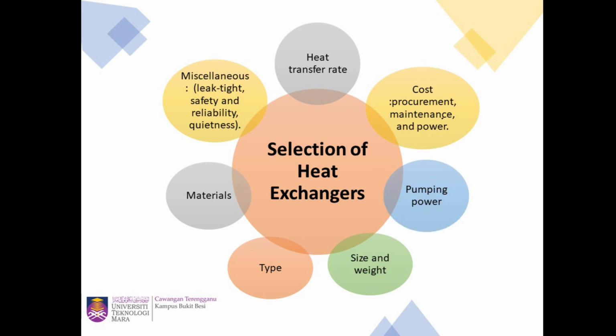Most importantly, the size and weight, the type of heat exchanger, and what materials are being used for the heat exchanger, so that we have to make sure it is compatible with the fluid that we're going to use. Last but not least are other miscellaneous factors, including whether the heat exchanger is prone to leaking. We have to consider safety and reliability, and also the quietness.